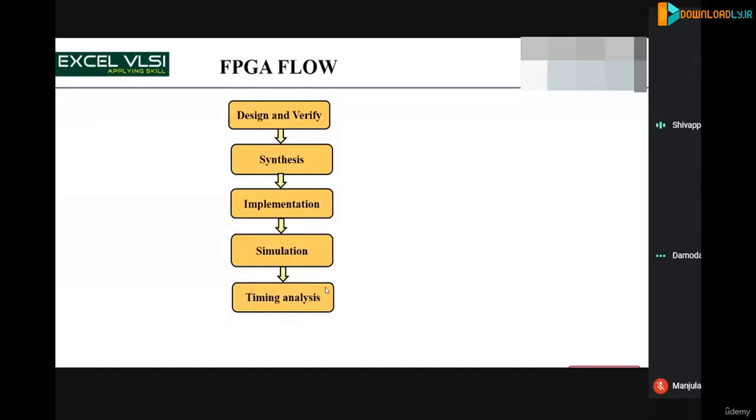And here also you do it in FPGA. Okay, and finally you generate the bit file using your Xilinx tool or any FPGA tool where you are targeting the design to be fitted, and that configuration file you are going to program to your FPGA board, so that the FPGA can function as you have designed.